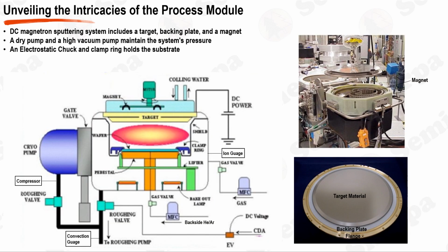The direct current, DC, magnetron sputtering equipment is a cutting-edge technology, imbued with an array of advanced features that ensure both the precision and efficacy of the thin film deposition process. One of the pivotal elements within this setup is the target, usually a disc-shaped piece of the material designated for deposition. The target material, secured on a supported backing plate, facilitates an environment conducive to efficient cooling and mechanical strength. This cooling function is imperative in the sputtering process as it aids in preventing the target material from overheating, thereby affirming the process's stability.